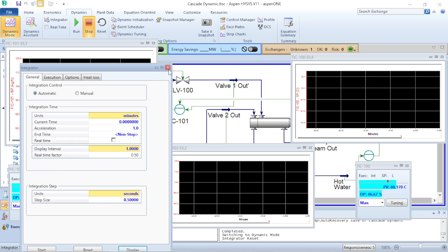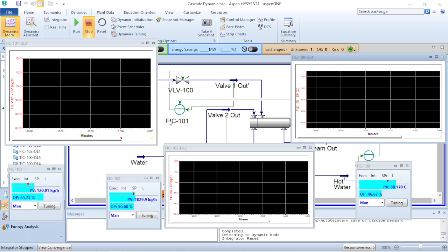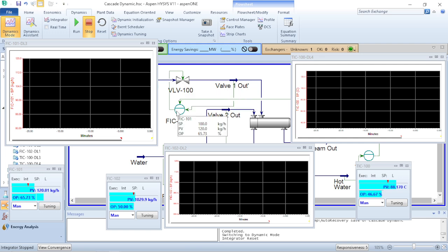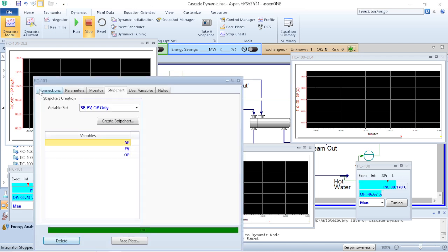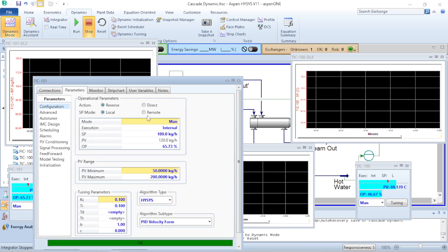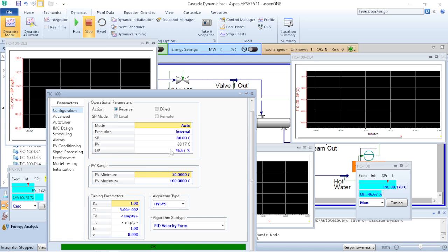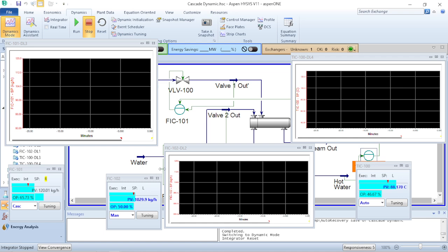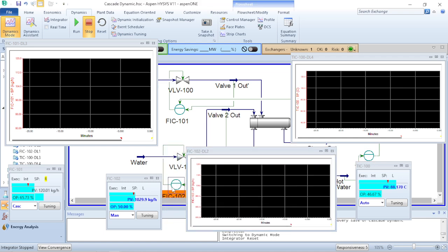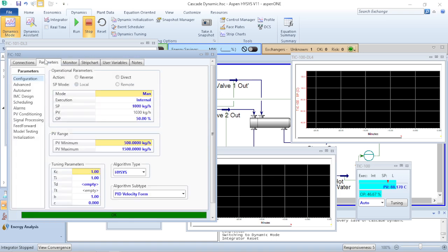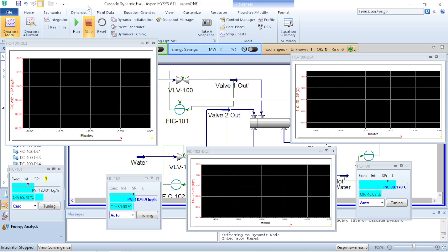All right. So let me close this. And I said we have to put all this in automatic. It's currently on manual. So I'm changing this to auto. Okay, no, this is going to be Cascade, because it's getting the signal from here. And then I'm going to put this here on auto. And this one would be auto as well. Okay, so we are ready to run the simulation and see what is happening.